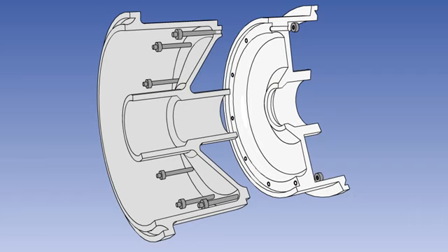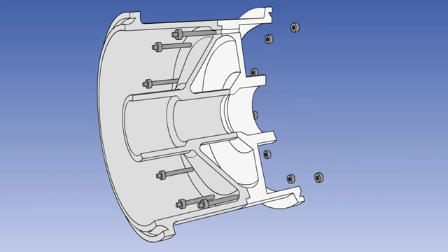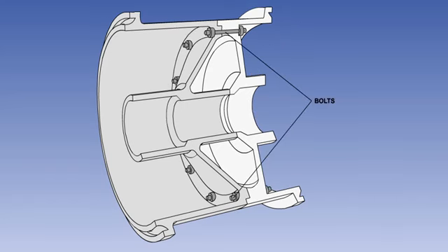The type of wheel most usually found on aircraft is the divided wheel. It consists of 2 half wheels matched up and joined together by bolts which pass through the 2 halves. The bolts are fitted with stiff nuts, or, if one half of the wheel is tapped, that is to say that the bolt hole has an internal thread cut in it, then each bolt is locked with a locking plate.